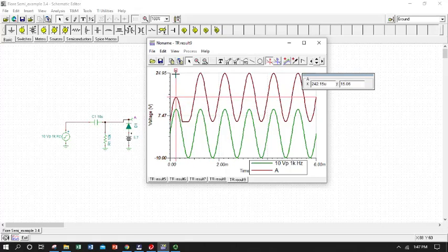So when we get to the top, we have our original 5 and a bit added to our 10 volt peak, and as we come back to our 0 inflection point, we find that we can't get below a point that is now reflecting that source minus the diode forward bias voltage.